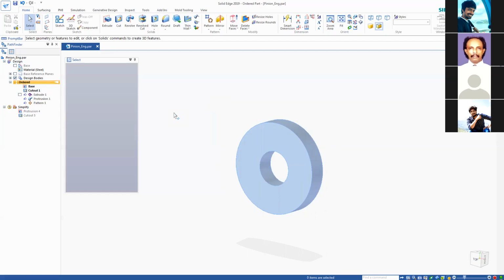Your design calculation may not yet be finished or finalized. Thickness can be changed. The diameter can be changed. The inner diameter can be changed. So you leave some options. Now, when you start like this, these are the base features. I know that I can change the diameter, then others will follow this.